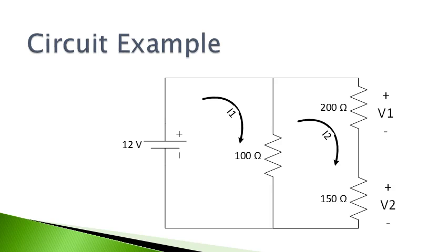If we look at the 12 volts on the battery here, then we see that as we go around this loop involving the 100 ohm resistor, there must be a 12 volt voltage drop across this resistor, where now the positive side of that voltage drop would be on the top of the resistor and the negative would be on the bottom.